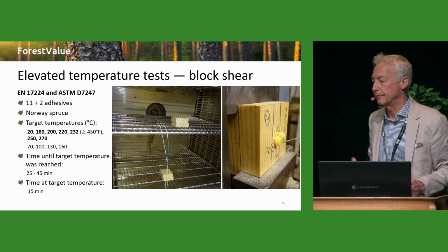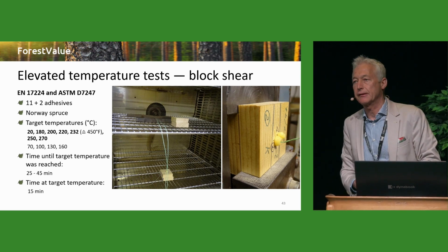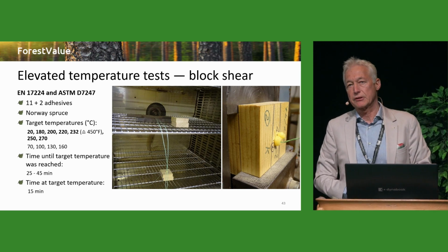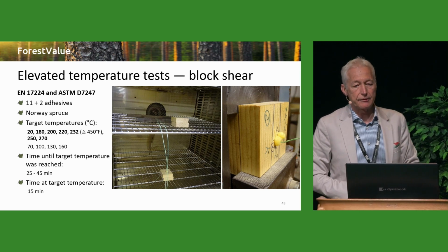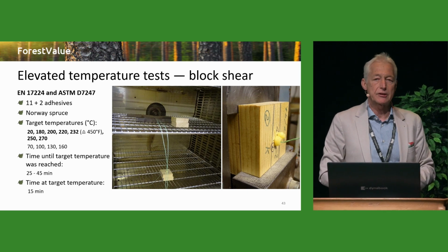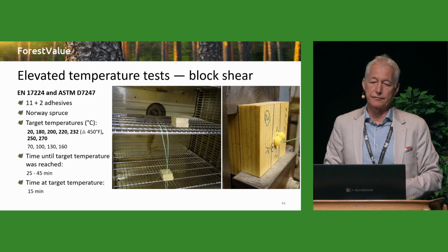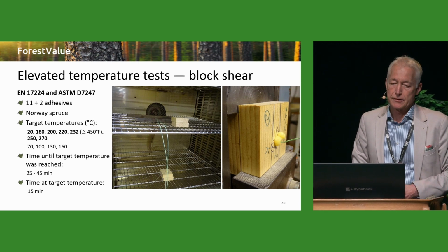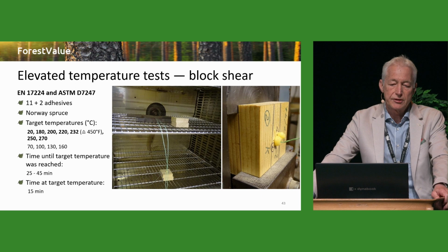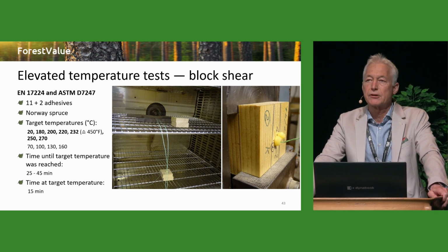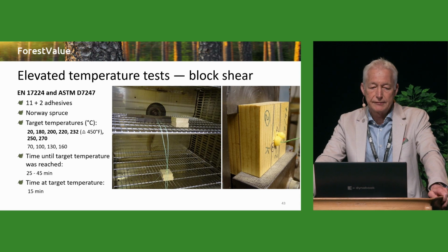These tests provide a test principle, but they do not specify target temperatures, and they specify an evaluation procedure, which, however, is not addressed to any classification of the adhesive. So we tested in different series these block shear specimens up to temperatures of 270 degrees.